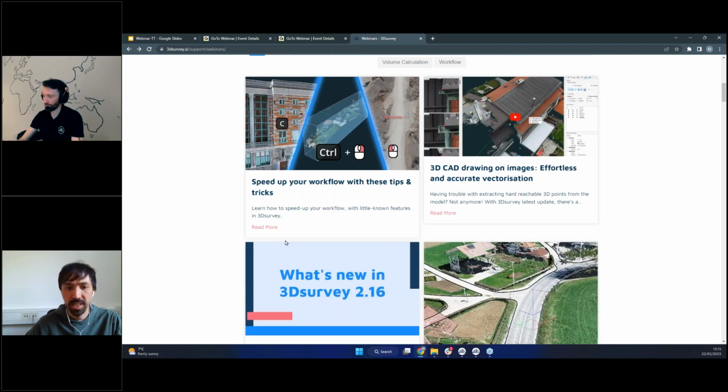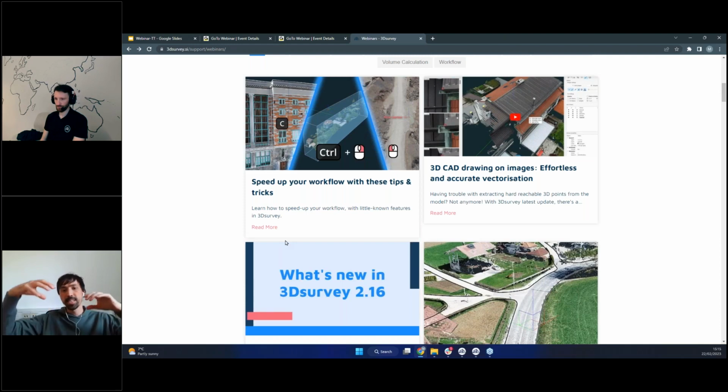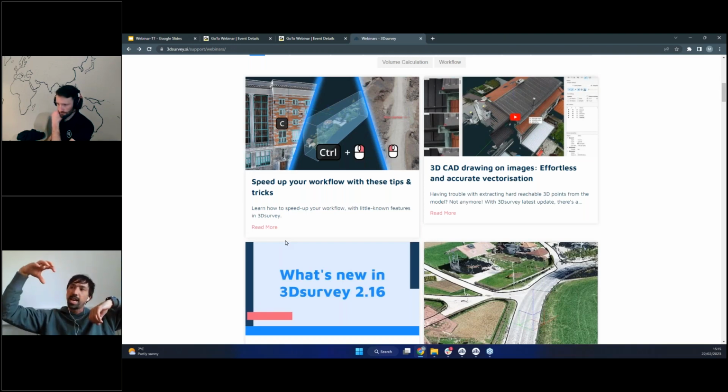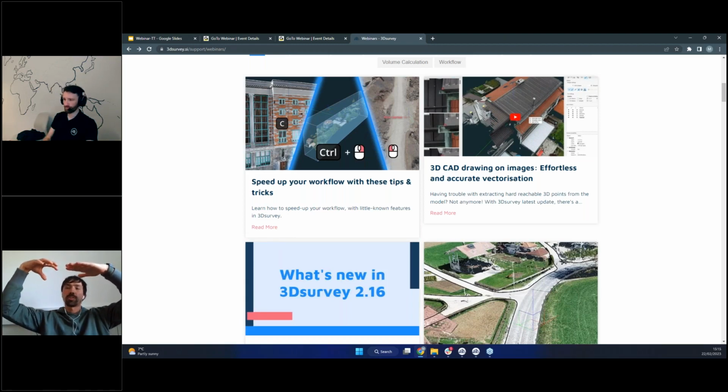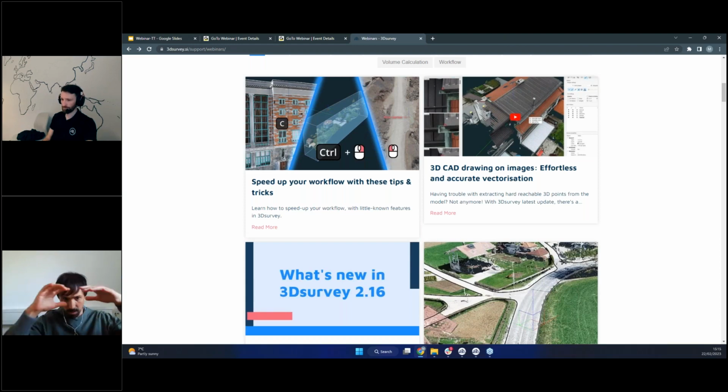If this is a 2-story building and it's not a big area, I would start with a simple grid at 60 meters to give you the confidence that you have everything, and then start to play with the circles or manual flight with camera angle. But in this case, you always need to build connections between the top-down images, which are 90 degrees down, and the side images. So don't go immediately horizontal. You need to go first 70 degrees, then 60, then 50, and so on. You need to build geometry between images.